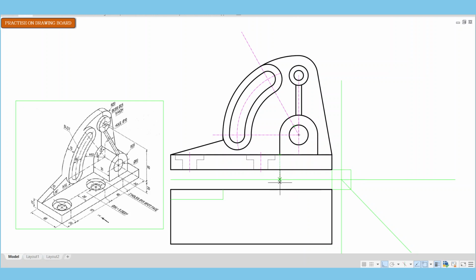So next, I'll project downwards this protrusion. So you see, I'm not drawing the projection lines. I'm only using the software to get the edges required. So that one comes downwards according to the dimension, so 35. Okay, and that will give me the top view of the protrusion.